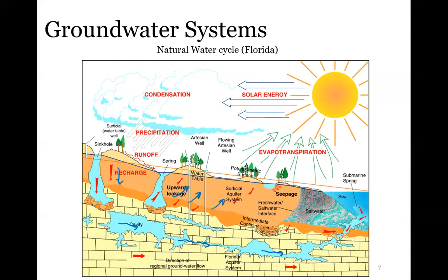And so we need to be able to understand the micro and macro permeability of our soil. Macro permeability would be the flow through these conduit systems that you see, like the little cave divers going through and everything. Micro permeability, the one that we care about as engineers and talk about here, is the flow through the pore space of the soil.